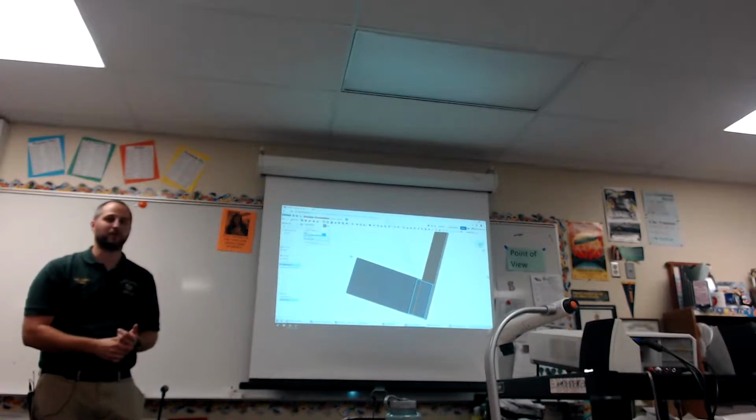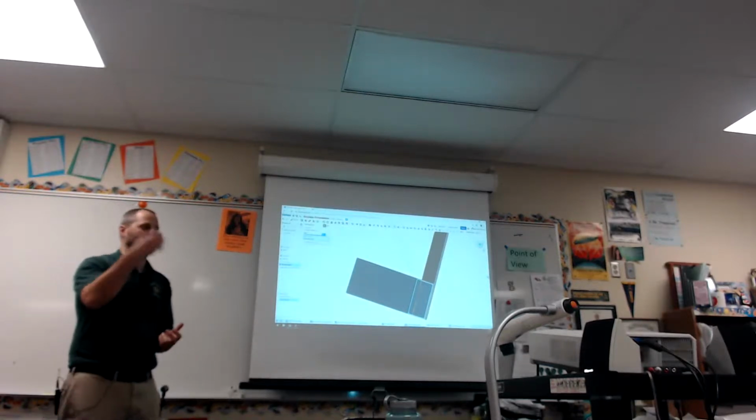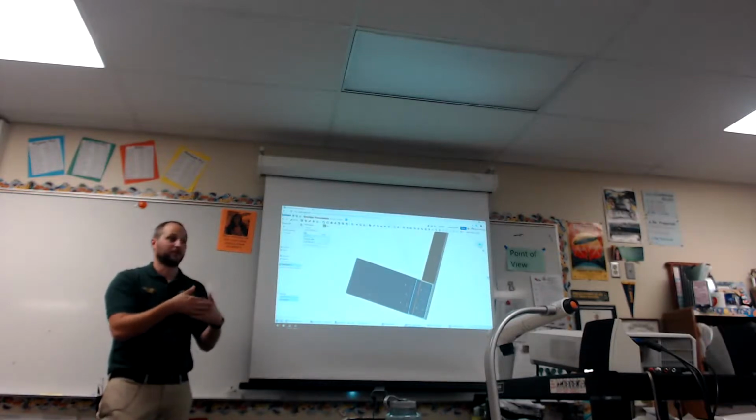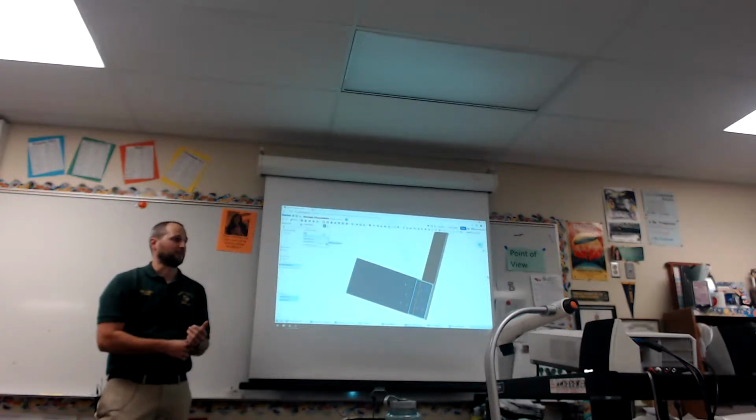It gets you a little bit easier way, and that's true in all Onshape part studios, to do through holes. So if you change the size of a part or the thickness of a part, you're not updating your hole sizes anymore. It still works and it doesn't cut through the other pieces.